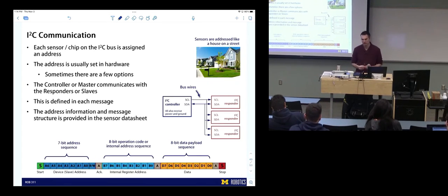Yeah. So for the homework problem with the light, when it asks for the address, it's referring to what type of functionality, like fading to whatever color, and that would be the opcode, which is the second part, right? Yeah. And then the data would be the specific values of RGB that you'd be changing, except it wouldn't be RGB. That's correct, it was the other one. So in that case, the use of the data payload changed when you changed the opcode.